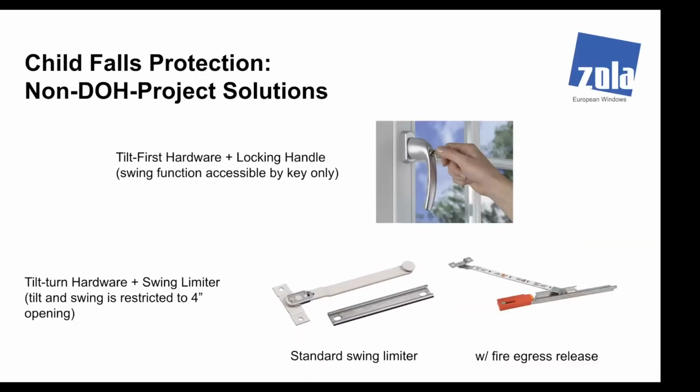Child falls. This isn't DOB, this is DOH, and I wanted to talk about the landscape of child falls. So child falls is a usage, not a code. You can have the same construction and building, and the question is, does your project fall under the Department of Health Child Falls Inspection Protocol? For moderate to low income rentals of a certain size or higher, the answer is yes. For condo buildings and for-sale units, the answer is no, because those are single family residences. They're not going to be inspected by DOH.